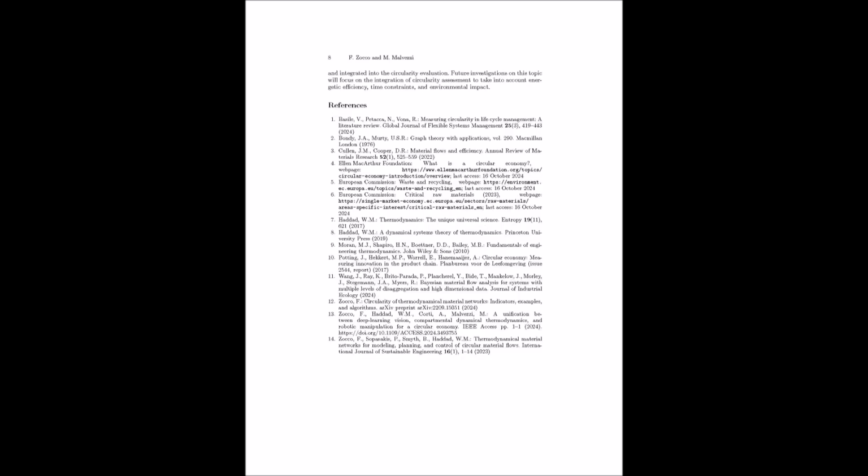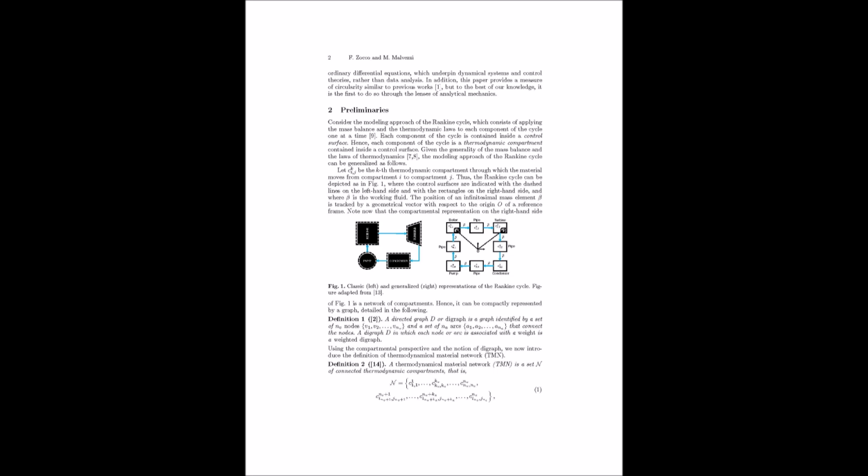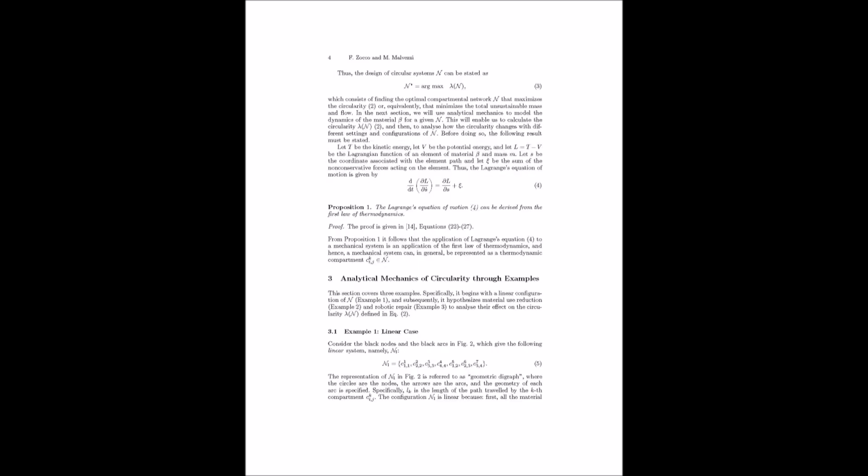But there's another way to reduce, and that's the second scenario. They look at what happens if the manufacturer simply uses less material to make the product, a 20% reduction. So instead of 1 unit of mass, they only need 0.8 units to make the thing. Right. And because that reduction applies to both the material from the mine and the material going to the landfill, our MUB becomes 1.6M. And that gives us a circularity of -1.6M. Which is better than the totally linear case, but not quite as good as using renewable materials. Interesting. So even though both strategies reduce material, using renewables makes a bigger difference in the circularity score. It's not just about using less, it's about using better materials, right?